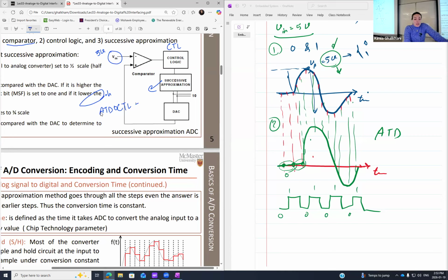And I asked you, hey, just power it on. That's the same thing. Information is given by the manufacturer. All you need is to go find the right register address, register label, register information, whatever you want to call it, and then bring it and set it to a certain hex value.